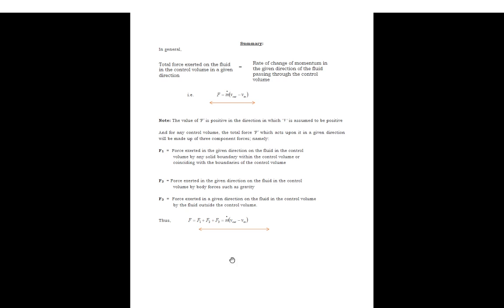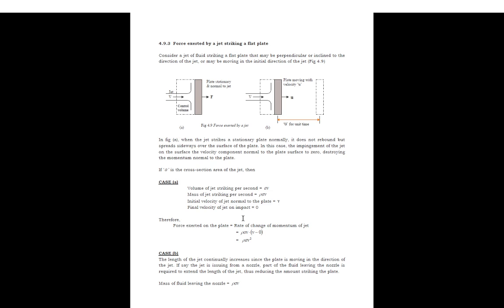So the pressure will create a force, the fluid has its own weight, and also there's an external force. So the rate of change of momentum is a combination of 3 forces: force as a result of pumping or pressure, force as a result of weight or gravity, and force as a result of external force. And all the total should be equal to the rate of change of momentum.